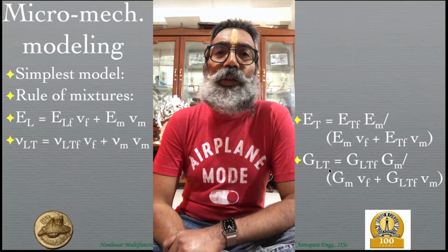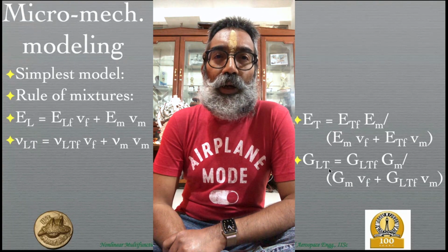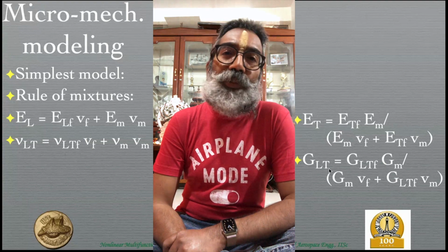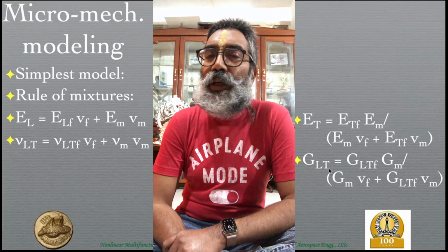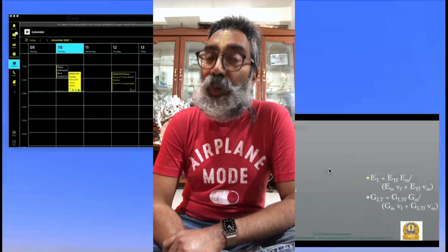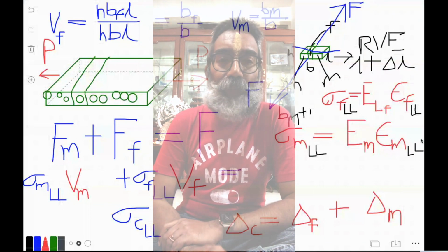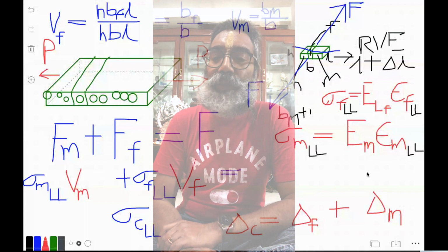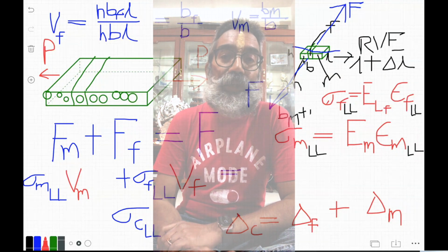But see, that's why the principle of superposition is valid. As long as we have a linear model, the principle of superposition is valid. We are talking about summing up the forces in one case, summing up the displacements in the other case. Many of these things are still valid. But the other things that we introduced in this particular example, we introduced the fact that the stress is proportional to the strain over here. That is a linearity. That can cause an issue in certain regimes.